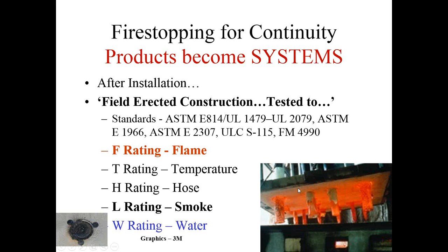The advantage is, yeah, you've got an ASTM or a UL standard for it, but the weakness of the test is that the material has only been in that area for 21 days, 30 days, whatever it takes to condition it. Secondly, the penetrating items never moved, nor has that floor ever moved, and that doesn't necessarily represent what happens in a building during the life cycle. Thirdly, nobody threw some cleaning chemicals or other chemicals on top of that penetrating item just to see if it'll be resistant to it, and then burned it.